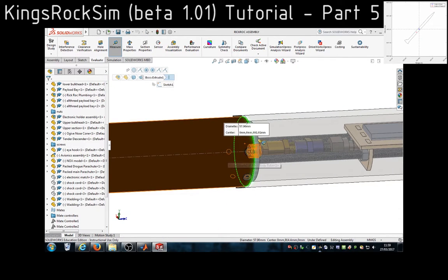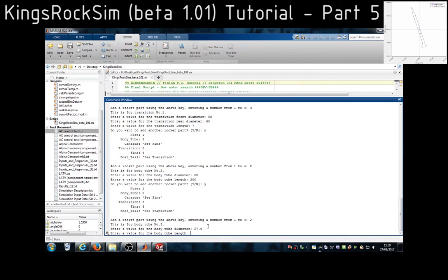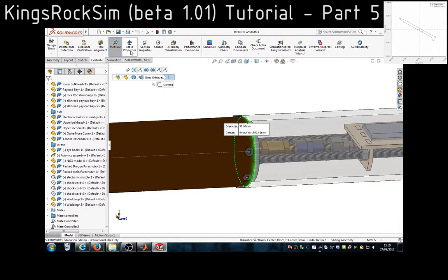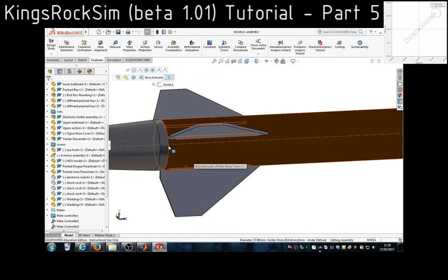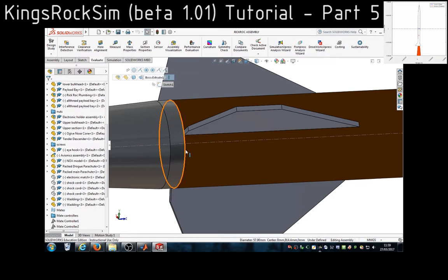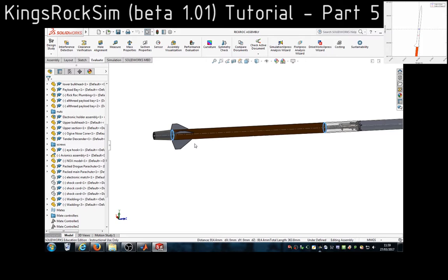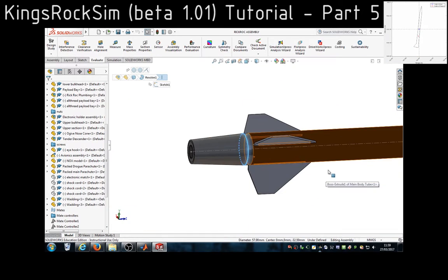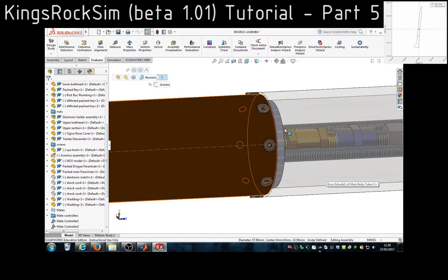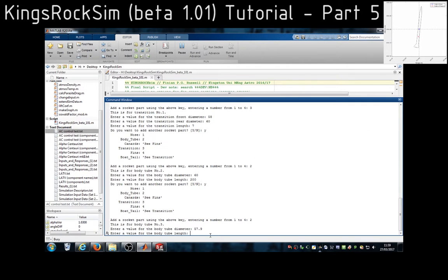in this rocket, has a length of 924.4mm. As you can see, there was a circular section that looked like it was part of the boat tail design, because it was, but it had a constant diameter matching the diameter of the body tube it was attached to, so I included it in the length of the body tube. Since you have to treat body tubes and transitions separately, even though that particular boat tail design is formed of what is essentially a small body tube and a transition following that.